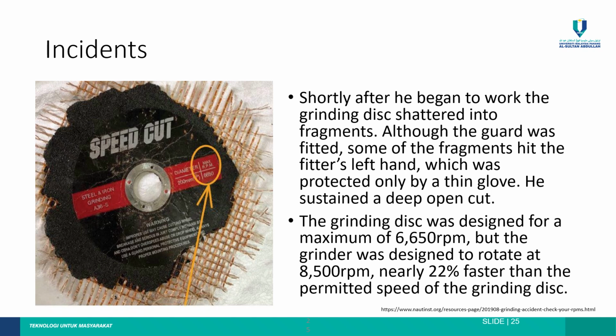So usually, if you are using rotating equipment, especially a grinder, you shouldn't be using rubber gloves or something like that. You should use proper gloves that could protect you in case this happens. Other than that, you should also always wear face or eye protection. At least it won't cut your face or your eyes. He sustained a deep open cut.